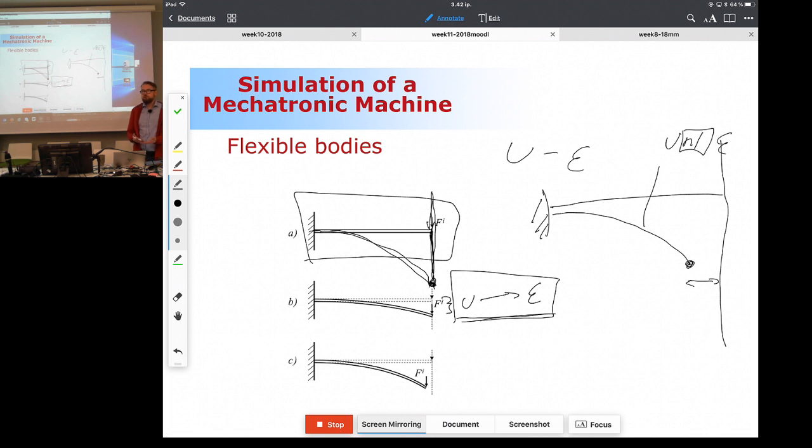This is one source of nonlinearity that is sometimes quite important when you're dealing with flexible bodies. Okay, let me try to make this clear to you. If you're dealing with a small deformation, then the linear relation between the strain and displacement is all right, and it behaves like shown here. In a cantilever structure, the free end of the cantilever beam remains on the loading line.